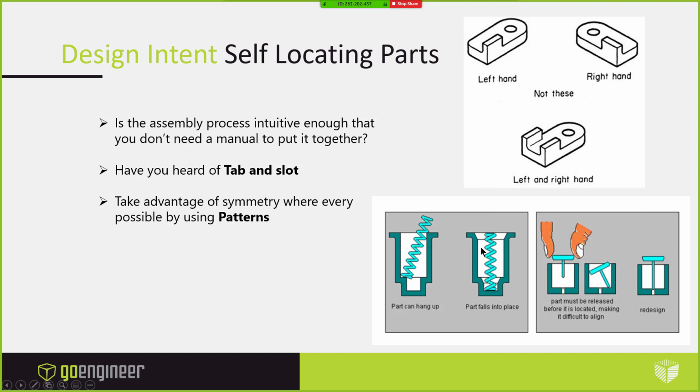I'm sure we've all dealt with that issue where you go to drop a fastener into a cylinder, and it doesn't fit right, or it's not quite long enough, and you kind of just have to guess when you drop it in, is it going to land in that hole, and you're fussing around with it. And as a consumer, yes, that can be annoying, but you probably only do it a couple times. But where this really impacts your company is on the assembly line, when the people assembling your product have to drop in hundreds of these little pins or hundreds of these little springs every day. And doing something as simple as adding a chamfer here makes it drop in a lot easier.